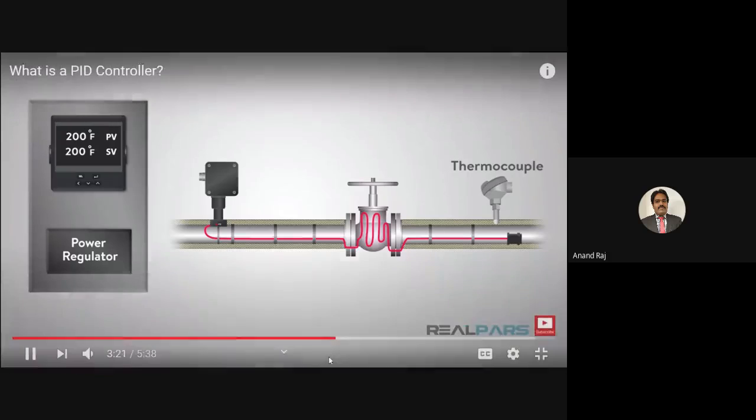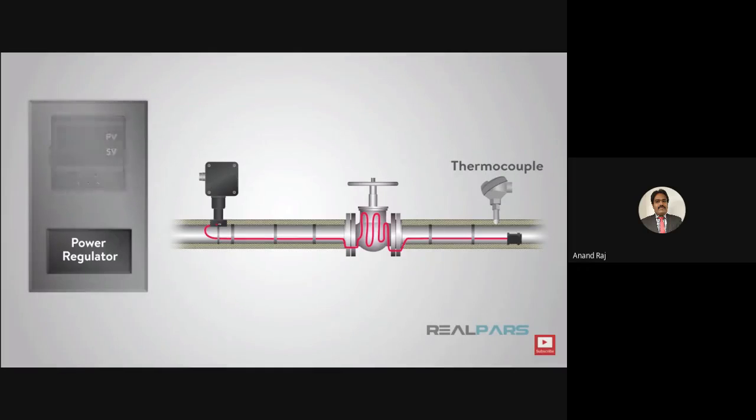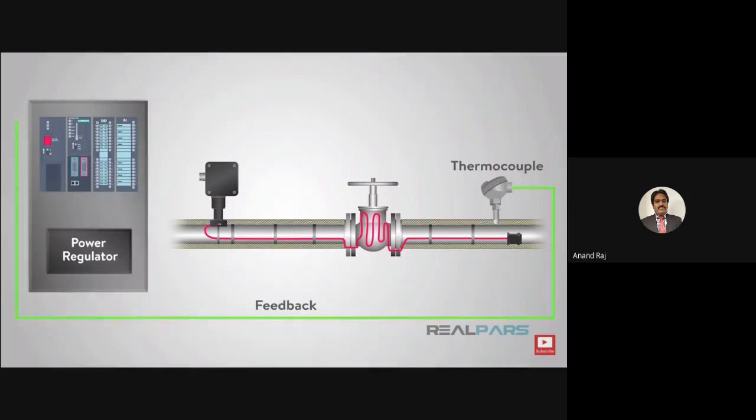We also have the option of setting up a PID controller with a PLC. Instead of the standalone unit, we can use the input and output cards already on our PLC. The process variable, or control loop feedback, would be wired to our input card and programmed into the PID. Our output being controlled is wired to our output card.